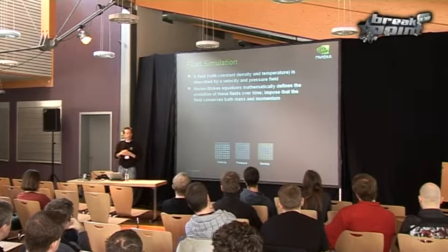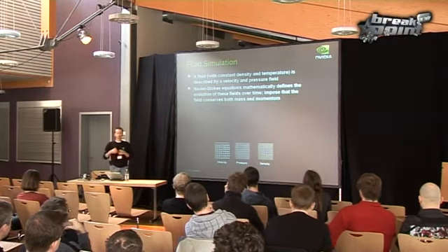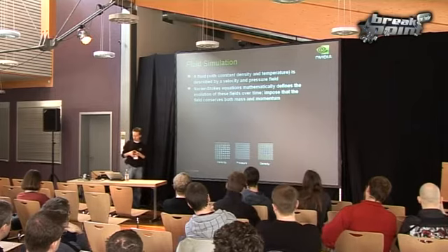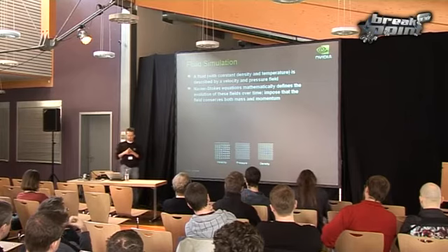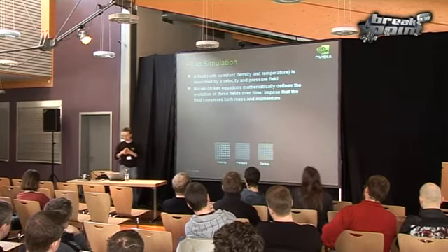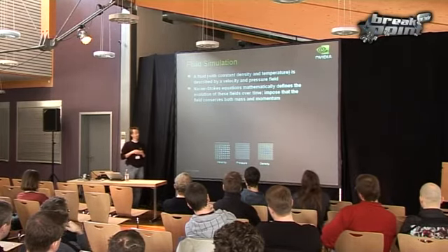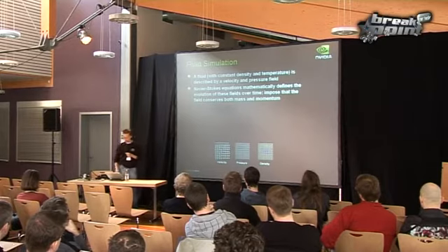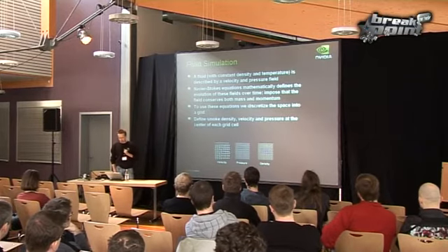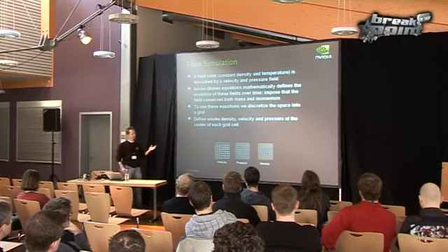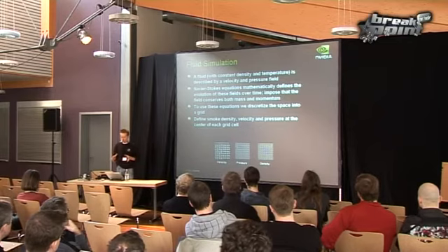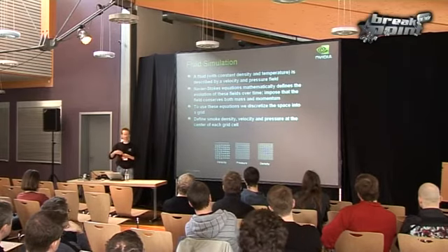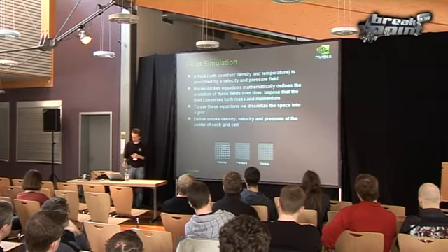These equations are actually physically accurate. They try to approximate what is actually going on in the physical world. The key points are that they impose mass conservation and momentum conservation on our fluid, so we don't have sinks in our simulation. Since we're dealing with digital computers, we need to discretize our space into a grid and then solve these differential equations, the Navier-Stokes equations, on this grid to evaluate the values of our fields at the new time step.